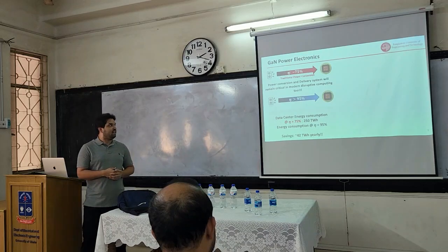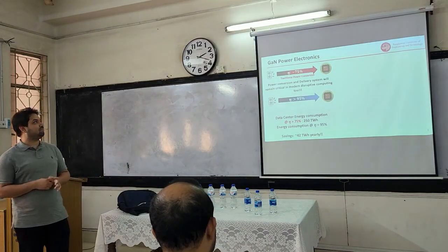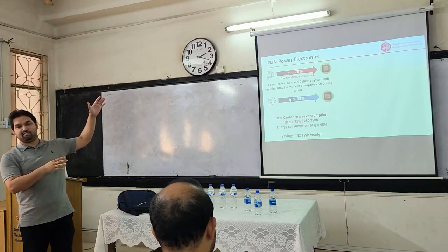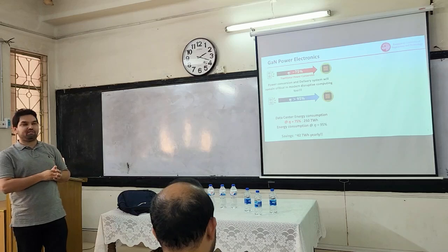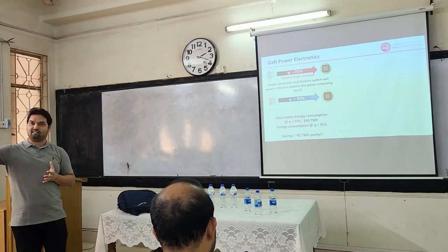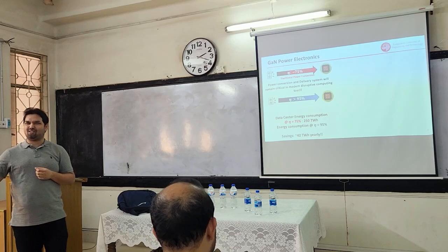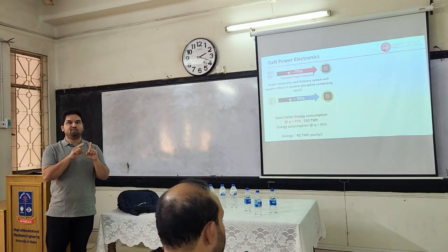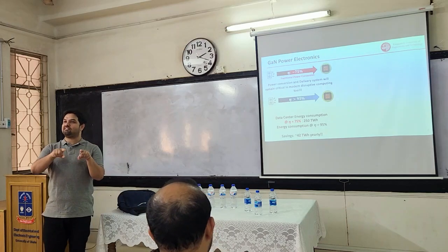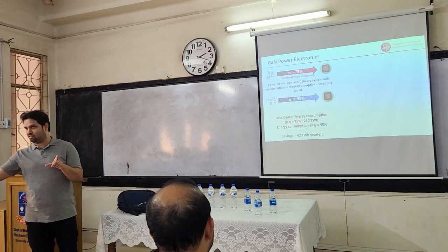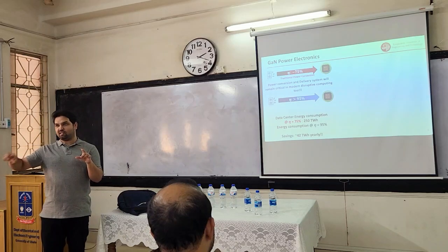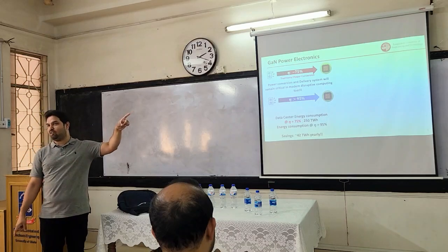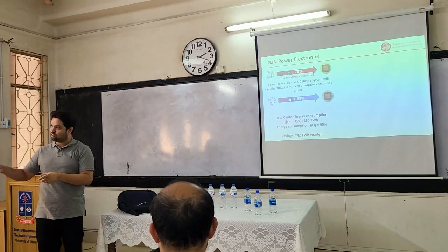Okay, so now let's look at why we are talking about power. Ultimately the power goes from the power lines or the wall adapter, to the wall socket, to the rack. Normally rack voltage is around 48 volts. If you input 48 V DC, your processor runs at right now 0.6, 0.7 volts. So from 48 to 0.7 you have to do a DC-DC conversion. And then from AC to DC, you have to go from 3-phase AC to 48 volts. That is also power conversion.